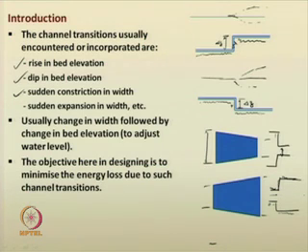Usually the change in width is followed by some change in bed elevation, because they are interrelated, or it may be required so that the flow or water level is maintained. As you have seen, open channels are mostly engineered, that is, we have used our engineering principles to design and implement them. So, we do not want much fluctuation in the water level.